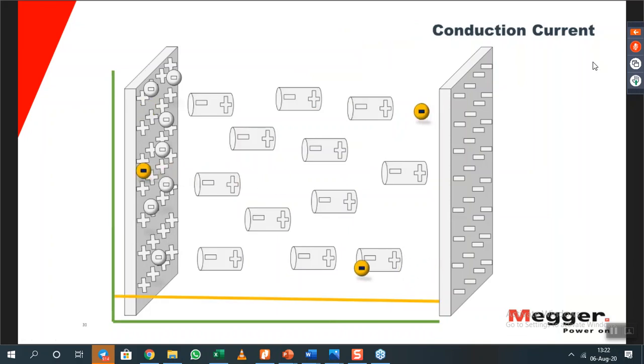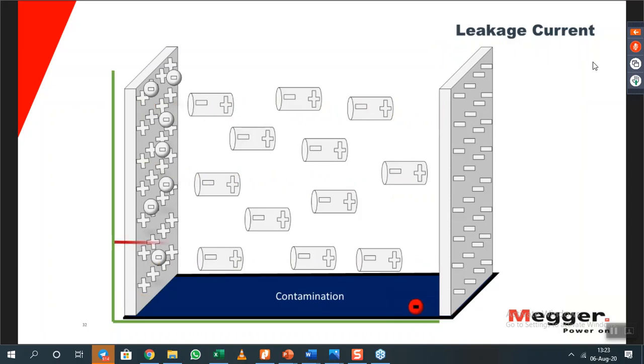And when we have this conduction current, because of the deteriorated insulation, as you can see here, there's no end for the conduction current. It will be forever as long as you have this deteriorated insulation. So over time, it will be infinite. See here? So you have a moving electron, then you have a conduction current. And if you have contamination and you miss cleaning it, it remains dirty, then you have the surface leakage.